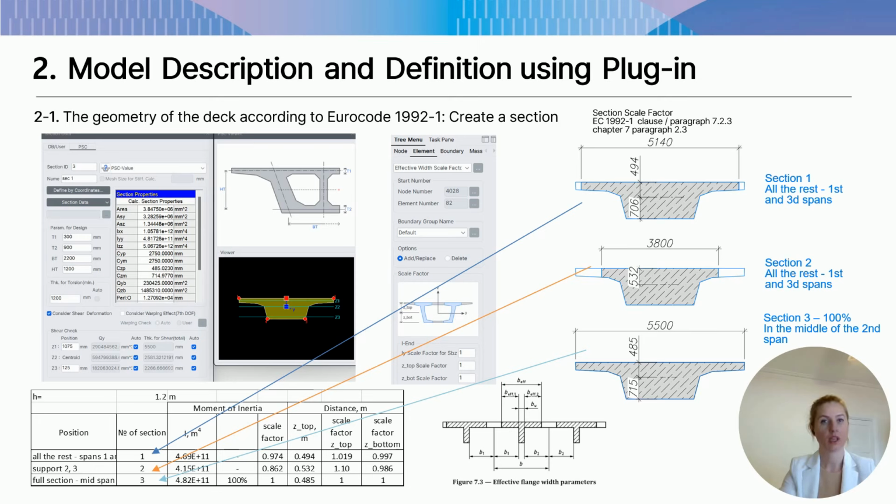Next, I created the biggest section, section 3, in the section property calculator and exported it to MIDAS. Fill in the section's dimensions there. I want to mention that there are 2 positions, Z1 and Z3. Those points will be displayed in the results. We will be able to check stresses at these points in terms of decompression, the most severe requirement at serviceability limit states.